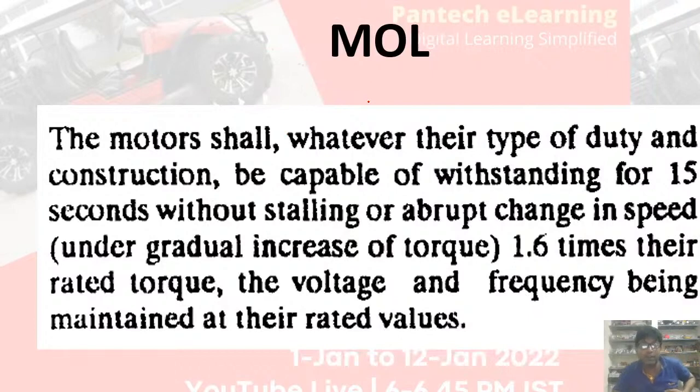Then the momentary overload test. What is the requirement? You have to apply 1.6 times the rated torque for 15 seconds. This is the guideline given in IS 325. You should load the machine with 1.6 times its rated torque for 15 seconds, and the machine should not stall.